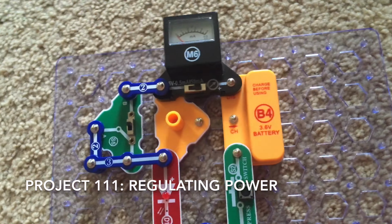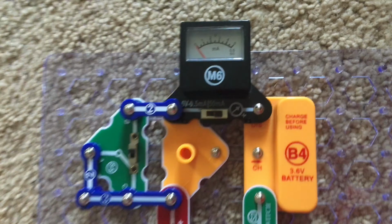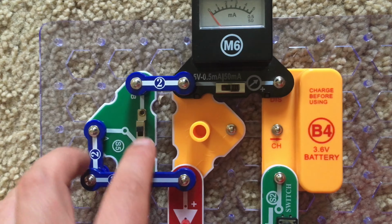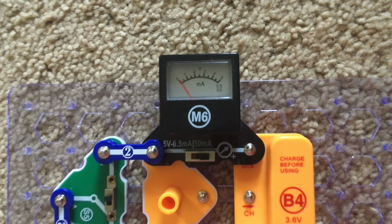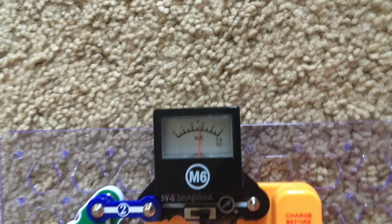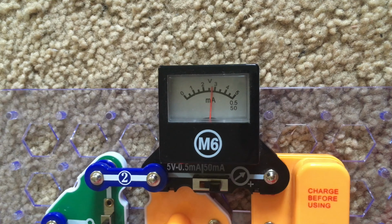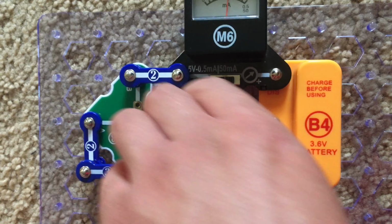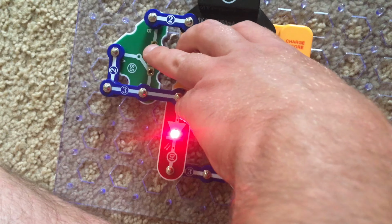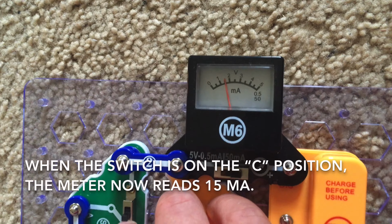This circuit talks about regulating power, Project 111. We have the LED, and we will set the slide switch to the B position to begin, and the meter to the 50 milliamp setting. On this setting, the meter reads about 27 or 28 milliamps. But when I move the slide switch to the C position, the LED will dim and the current drops to 15 milliamps.